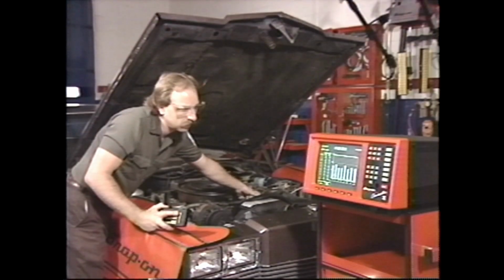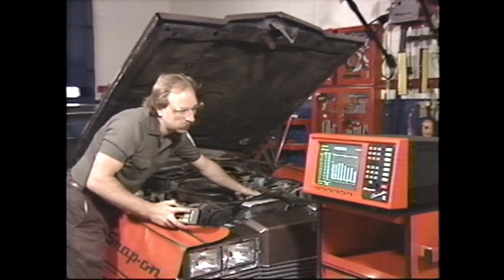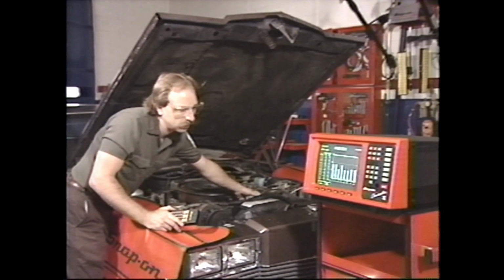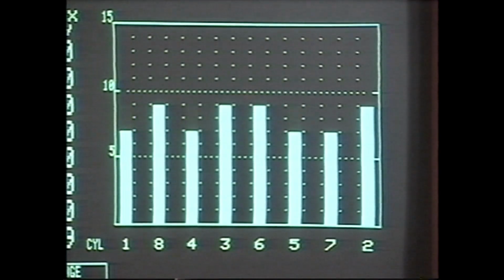As a general rule, if the minimum or maximum kV values change adversely during a snap acceleration test, the problem may be inside the cylinder. If the kV values do not change, the problem may be outside the cylinder.